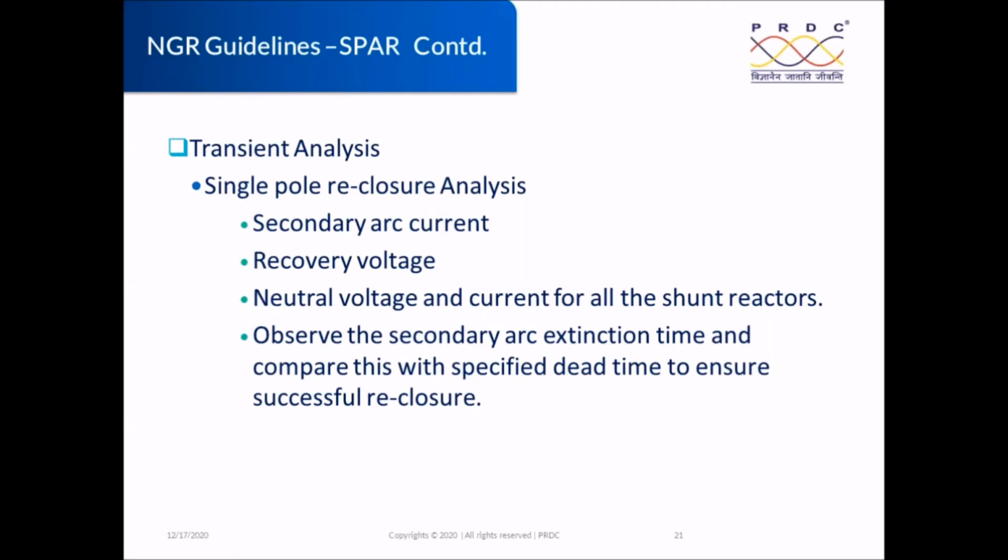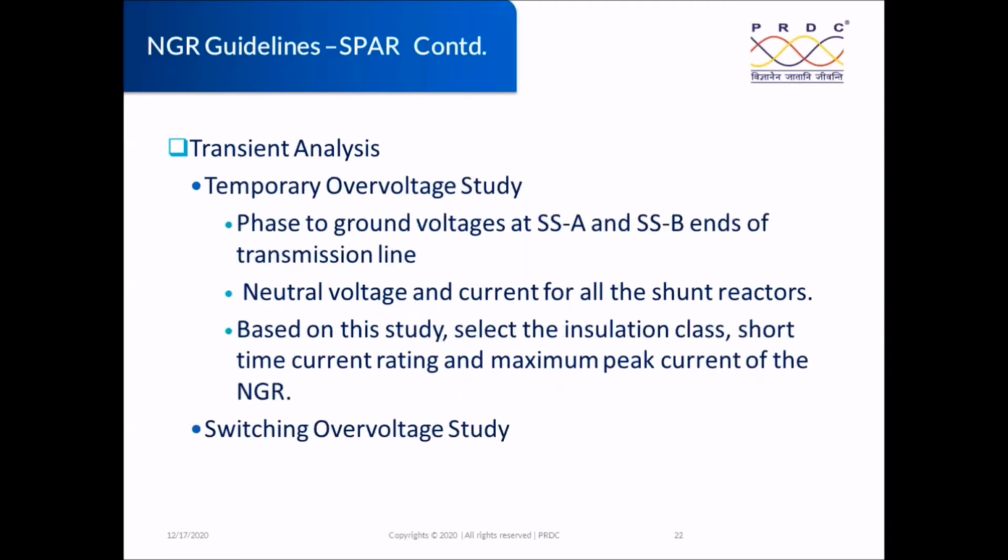But the only thing is, once you identify that particular NGR value to have the successful auto reclosing phenomena, we have to check again that it should not cause any resonance problems under different stuck breaker conditions. So that is again something we have to cross check here.